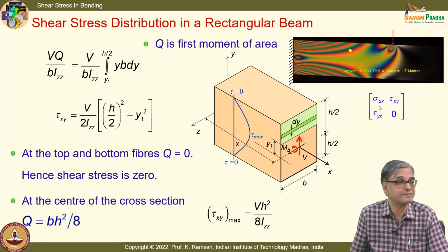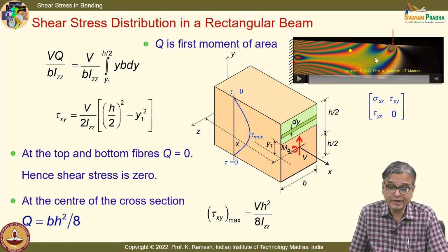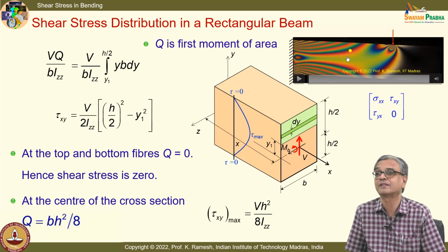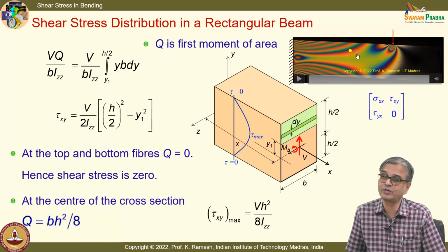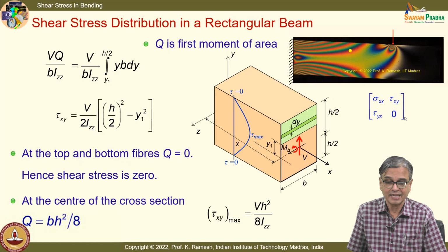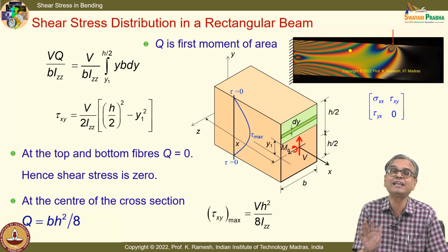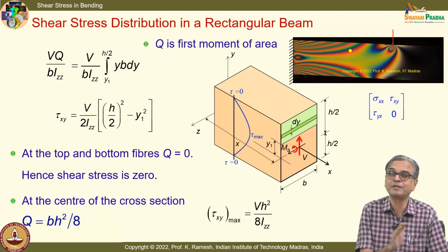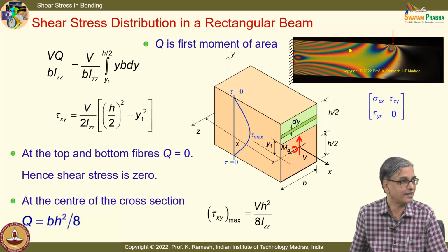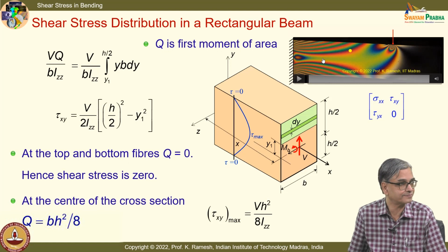is varying linearly, and your bending moment also in a cantilever beam varies linearly from the loading point to the fixed end. But I have this, rather than being a straight line, it is curved. Where does that curvature come from? You know, photoelasticity plots only sigma 1 minus sigma 2, and you are putting tau xy as non-linear. So your variation of sigma 1 minus sigma 2 is not linear over the length of the beam for a horizontal line. Okay. So you have this as a curvature.